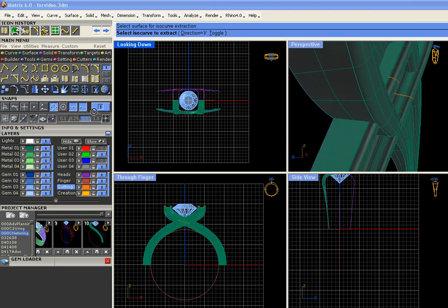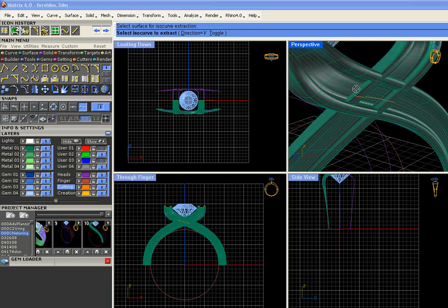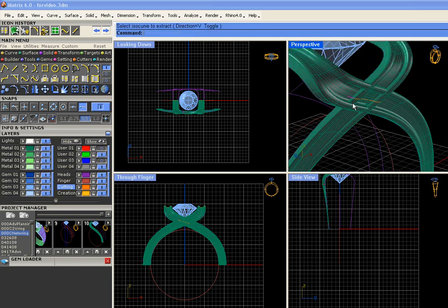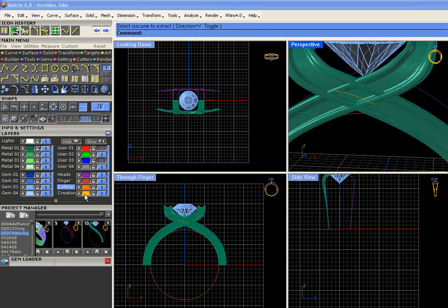Sometimes it wants to do weird things. Turn off the other O-snaps if it's not behaving. Also make sure you select the correct surface, that'll help. Okay, let's right-click on orange and join these all together.